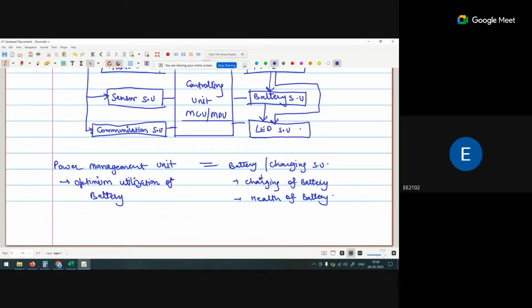Okay, the thing is that, for example, nowadays I design one earbud, and I want to give it a lifetime of 30 hours. Now, as per the customer requirement, the customer wants my earbuds to work for 50 hours, and for the 50 hours of working I have to make some changes. I can reduce the power of the LED. I can use a small LED, so the power requirement for the LED is less. That is one change I can do.